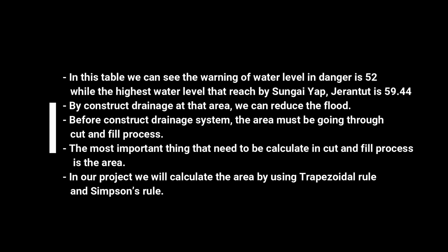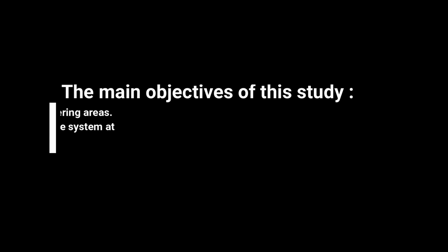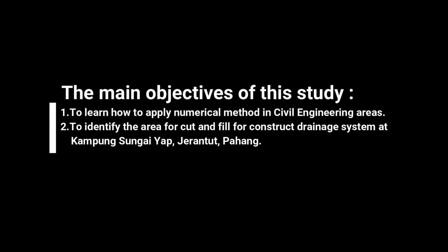Before constructing the drainage system, the area must go through the cut and fill process. The most important thing that needs to be calculated in the cut and fill process is the area. In our project, we will calculate the area by using trapezoidal rule and Simpson's rule. Objective of study. The main objective of this study is first, to learn how to apply numerical method in civil engineering area. Second, to identify the area for cut and fill for constructing a drainage system at Kampung Sungai Yap, Jerantut, Pahang.